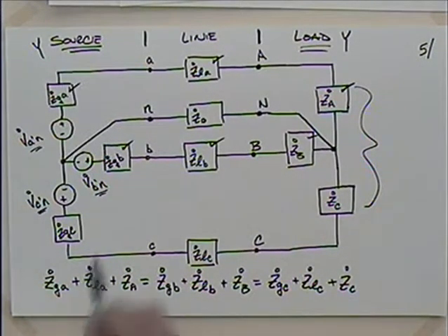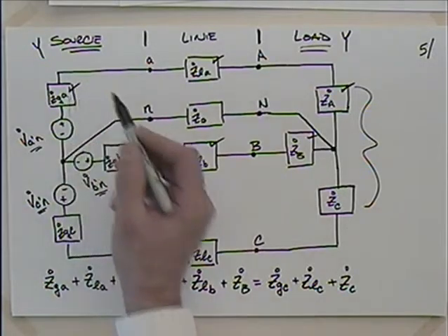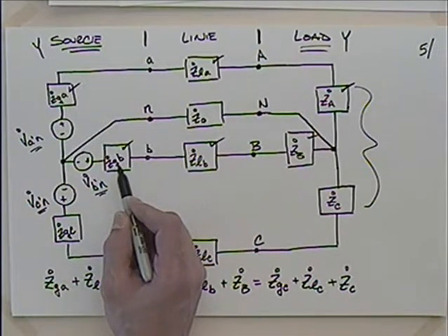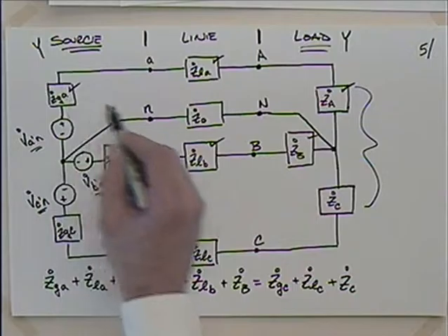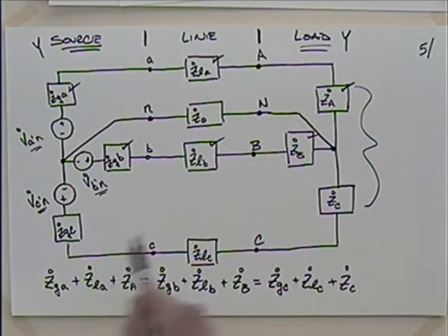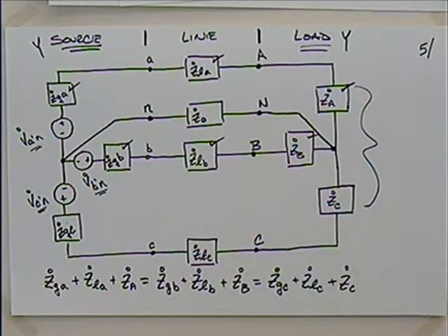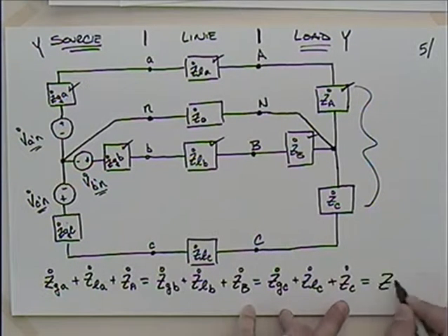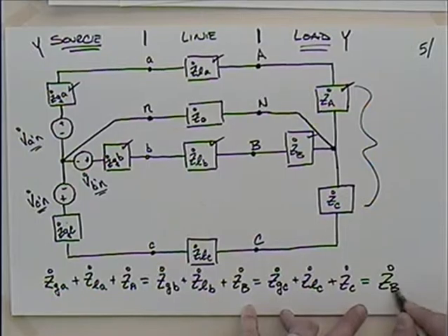Okay, so just because this impedance here isn't quite the same as that impedance there doesn't mean that it's not balanced. If you look at the sum, this plus this plus this, then that had better equal this plus this plus that. That's pretty common to make sure that those are all the same, but really we only need the branch to total out. Okay. Well, if all of this, we could call this Z for the branch. Okay.